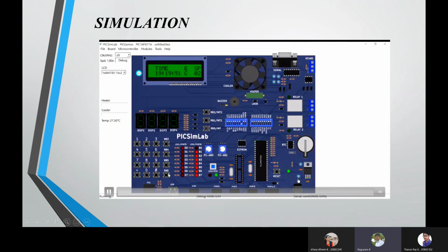The push buttons RB2 and RB1 are used for gear shifting, and push buttons RB3 and RB4 are for navigating up and down, and a potentiometer is used to control the speed of the vehicle. The data of these sensors is displayed on this display, and to extract the data from this black box, it requires a password. In our simulation, we gave the password as 2424.